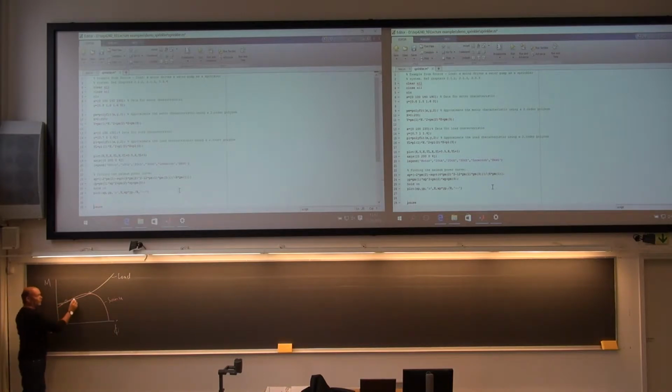If you go on the other side, your source is stronger than the load. Then you have additional energy, you might think, additional torque. Then it will speed up the system. Then it will continue to move away from this operating point. So this one is an unstable operating point.